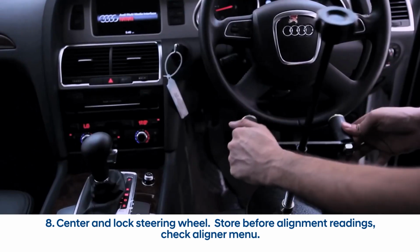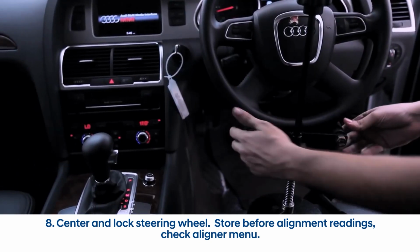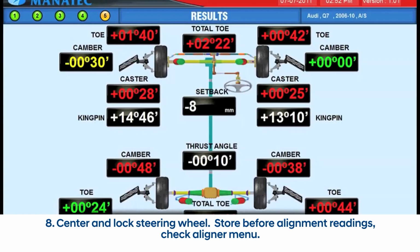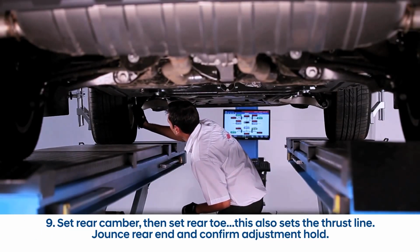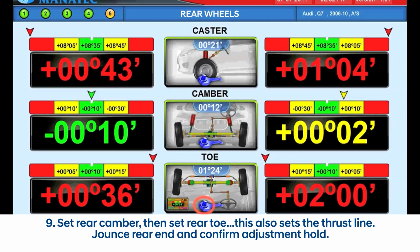8. Center and lock steering wheel, store before alignment readings, check aligner menu. 9. Set rear camber, then set rear toe. This also sets the thrust line. Jounce rear end and confirm adjustment hold.